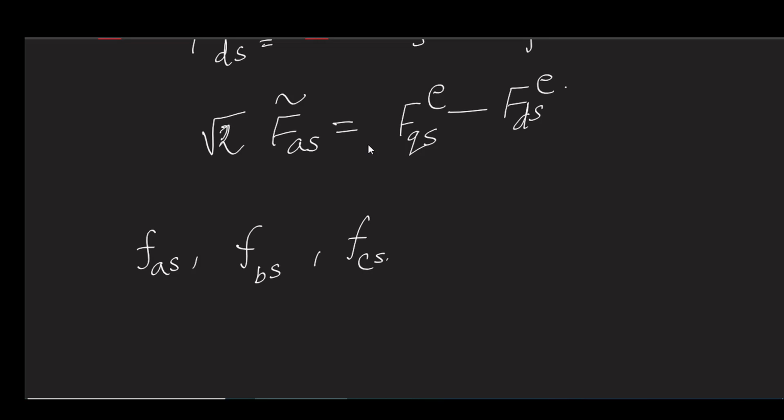Now, if I make you confused by saying that transformation matrices remain always invariant, that has nothing to do with your actual phasor. The transformation matrix is always the same, and what type of linear transformation it will generate depends only on the difference between omega e and omega em.